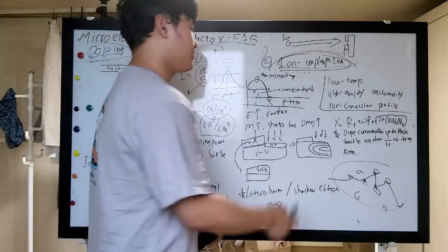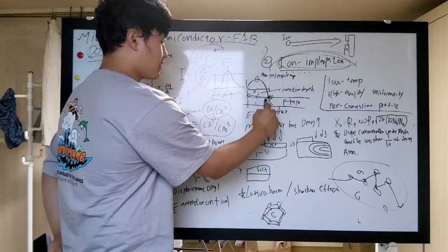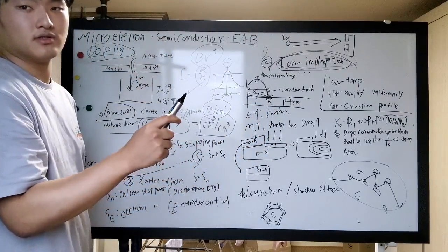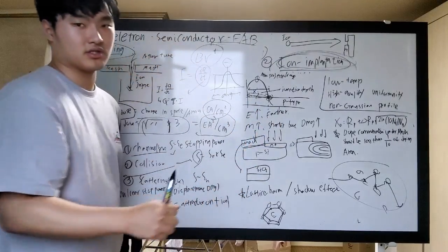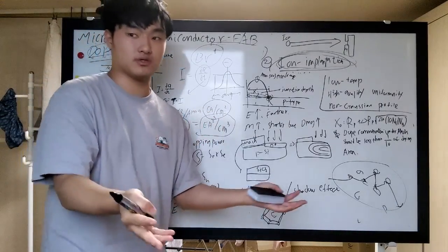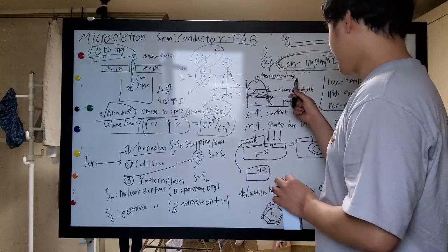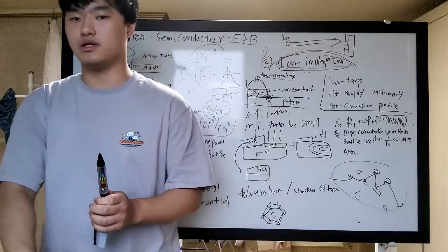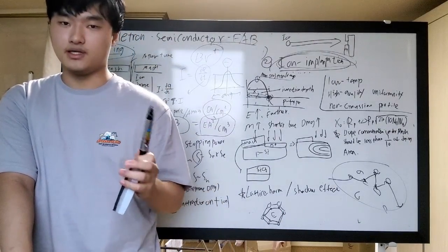original silicon area. So here is the interface between the dopant area and the p-type silicon, the original silicon that is the target of the doping. This distance will be called the junction depth. It means how deeply the junction has been created. And the mean projected range just means the range where the ions will mostly be injected.